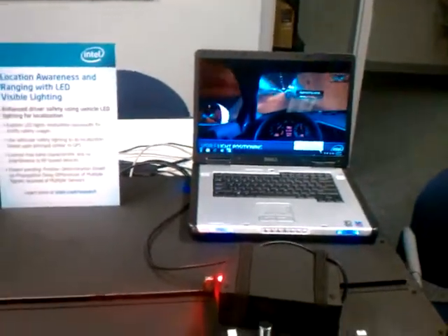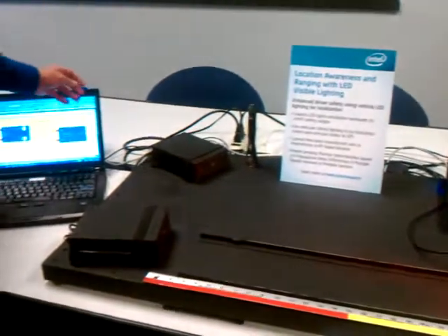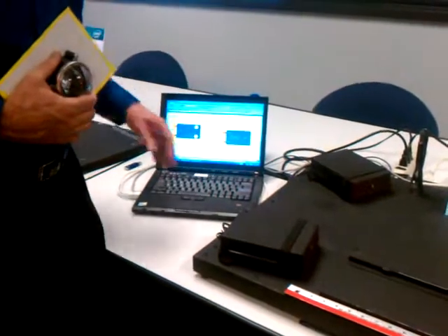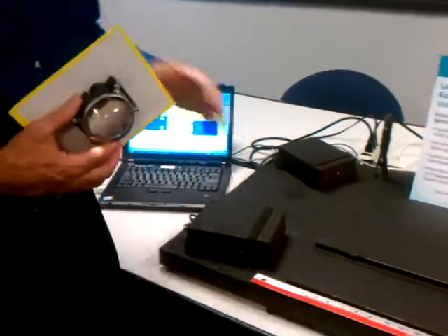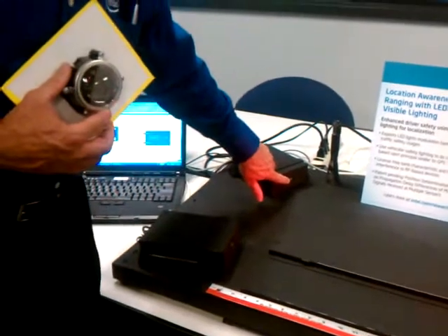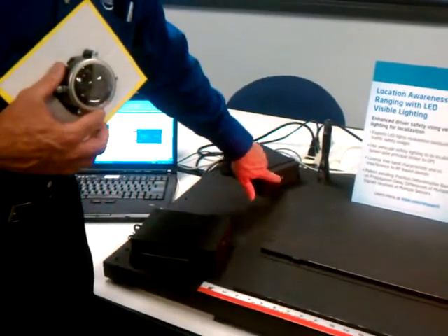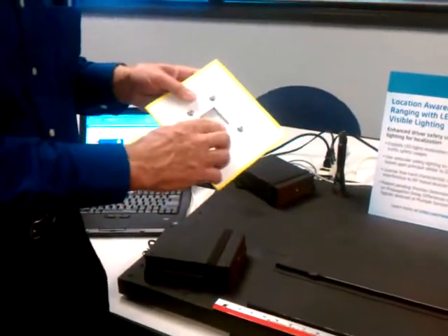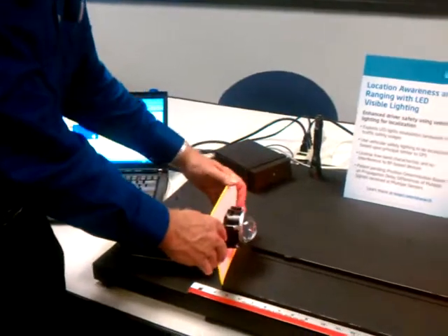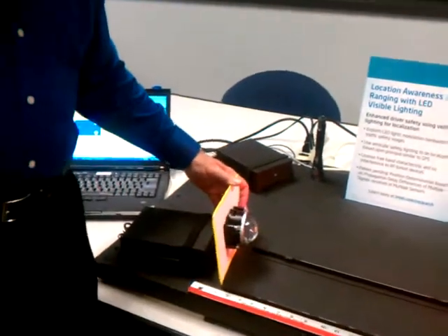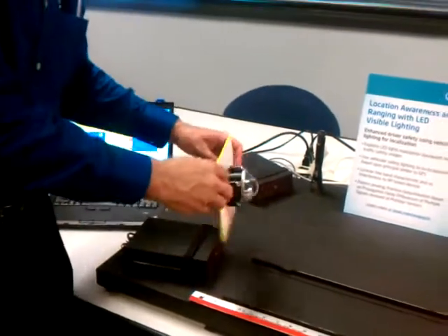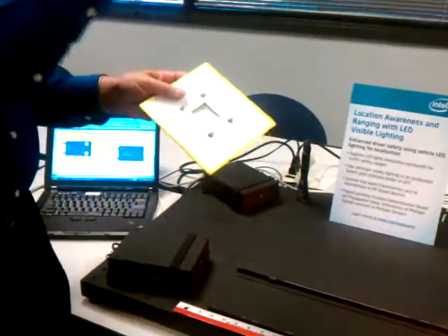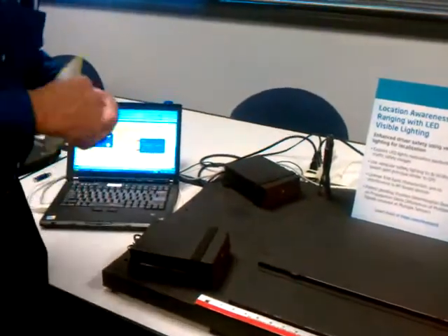Now, in the case where we have multiple lanes of traffic, one might ask, well, won't that be a confusion for your sensors to process? And the answer is not really, because what we would do in a real deployment is we would not have a single photodetector. Rather, we would have a lens system with an array of photodetectors behind it, much like a digital camera. And much like a digital camera, it has no trouble seeing the multiple light sources, which show up as modulated pixels in the image array. We just have to find those pixels that are ingesting data.